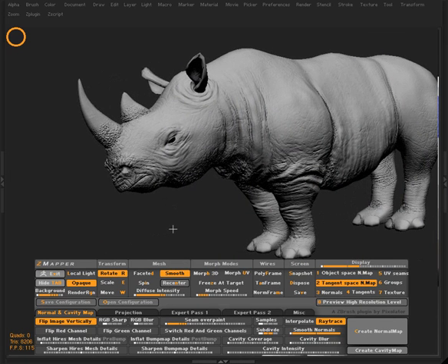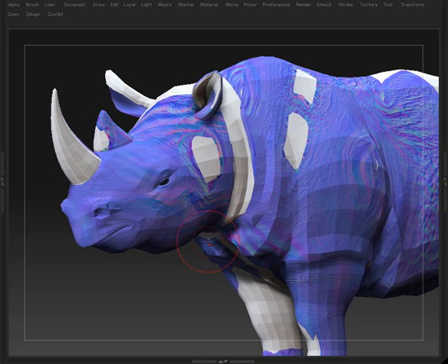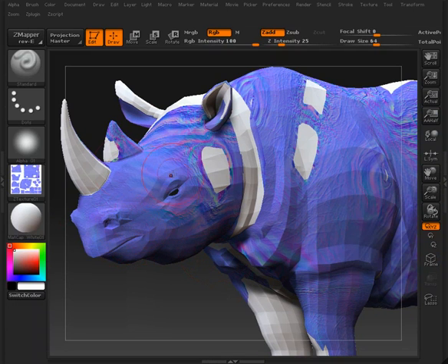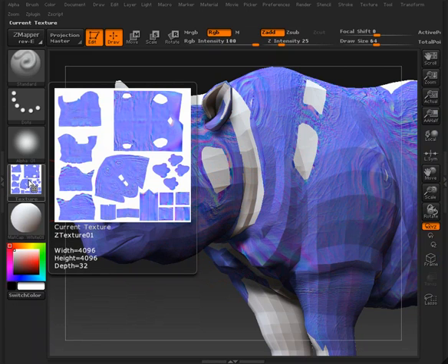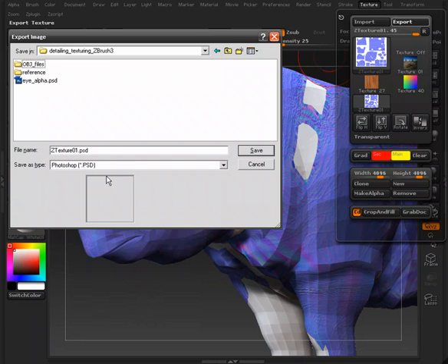So once you're finished and once you have your normal map generated, what you can do is now just press the escape key on your keyboard, and it's going to look like this image is a little bit wonky, but that is completely normal. It just automatically flipped it for us when we were leaving the ZMapper, right? Because we had chosen that Maya export option. So it went ahead and automatically flipped it. So now this normal map is ready to be exported just like before. So we'll go up to Texture, Export. Alright, and we'll call this Rhino Normal. We'll use the same bitmap.